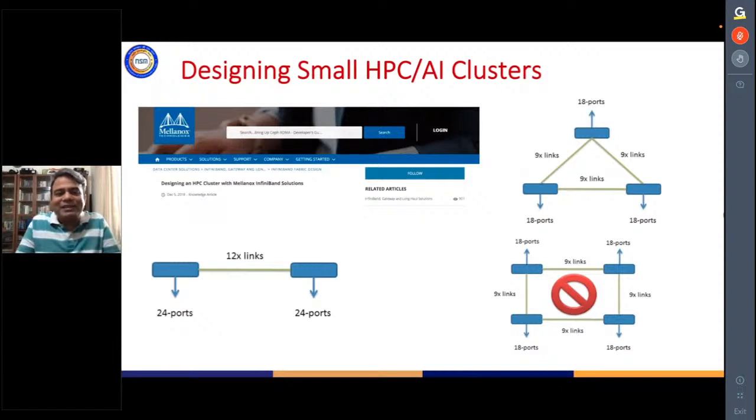It's a very simple way of saying that I cannot take a 2-inch by 2-inch die, because then my yield is not very high. So the industry always tries to get the best price performance, and based on that, the largest radix, or the largest port count network processor that you see today, is of the order of 40 ports or 128 ports, ranging between that.